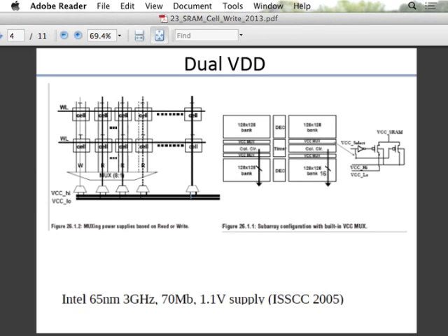So the VDD line here acts like just any other signal line. Okay, and then you mux between these two. The reason you can do this is that the current drawn from the VCC line here is very small. The cells are tiny, and you have many of them, and each column has its own VCC line. Normally you don't want to do this kind of thing because this mux will put in additional series resistance and really degrade the operation of your circuits. But in this situation the cells are largely static, they don't switch much, they don't draw too much current, and the only current you draw is leakage current, and when you're writing into the cell or reading there is some current, drawn from this vertical line, but the currents are very small.